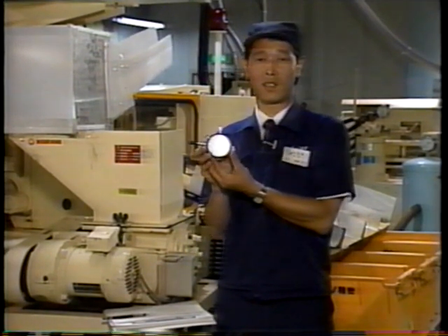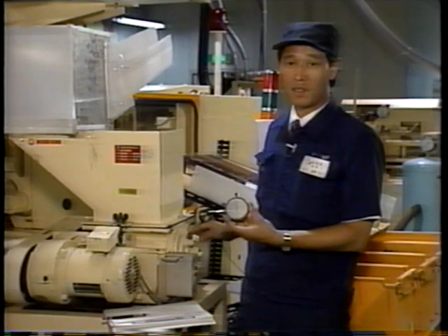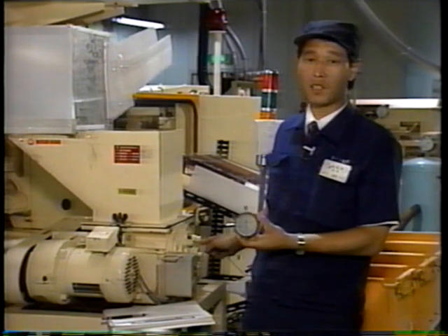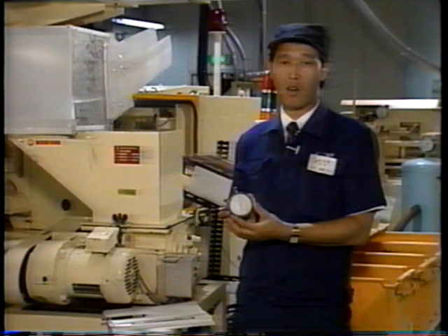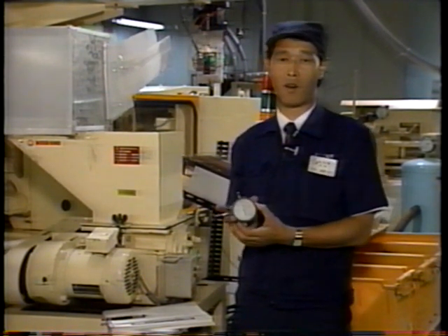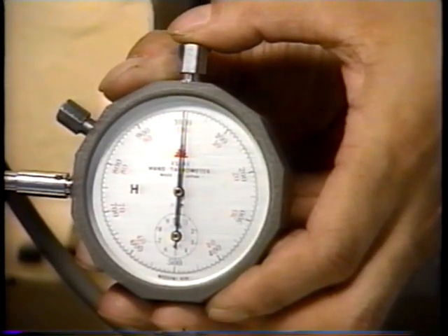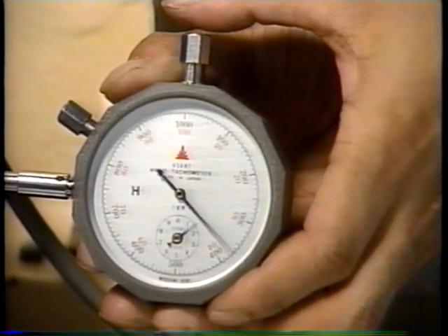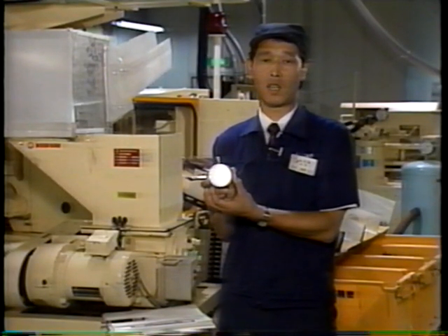As you can see, I'm holding a revolution gauge. As the cogs of this grinding machine behind me turn, this gauge measures the revolutions of the shaft. In order to decide the cycle of checking for belt wear and tear, as well as damage to the bearings at an early stage, we have to collect data for a whole year to get an adequate picture of what's happening. We use gauges like this to measure data such as revolution loss and other variables.